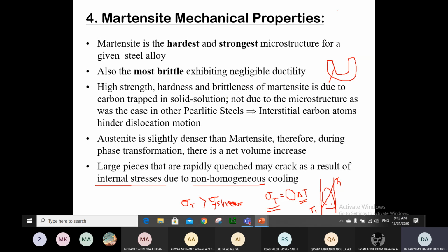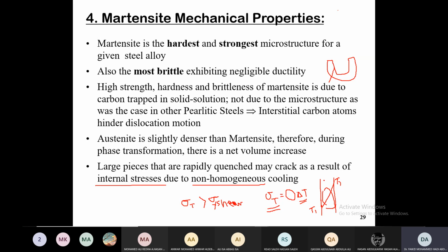And even if it does not cause that, in metals there will be an internal stress or residual stress which develops in the material and stays there. If this happens, then we have a problem, because the material would not really be good to use. Why? It loses its full capacity as a material to be stressed. There is a residual stress, and then if I apply another load, both loads will be acting there, so the load carrying capacity of the material reduces.